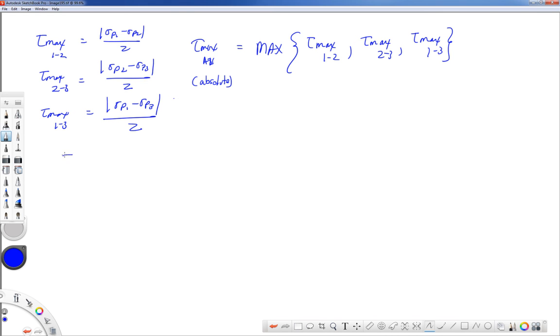But just to give you an idea of what we need to do, if we were to arrange the stress components in a matrix like this, it's symmetric, where we have the shearing stresses on the off-diagonal terms and the normal stresses on the diagonal terms, and solve what is called an eigenvalue problem, we will find the maximum stresses.